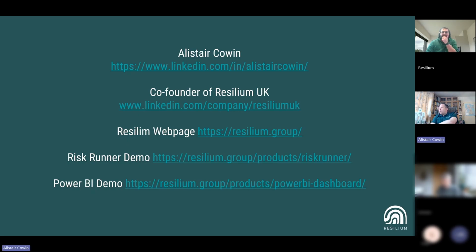And I've just seen another question about ALARP: another way to determine. So this is a really interesting one, Mohammed. I think ALARP can only be determined when you have an understanding of your system. So, are you doing enough? Is what you have working well enough for you? I don't think you could use ALARP to understand the health of your barriers, but the health of your barriers informs your ALARP position by saying, if we said we would do a thing and we're not doing it, we're definitely not in the ALARP camp.